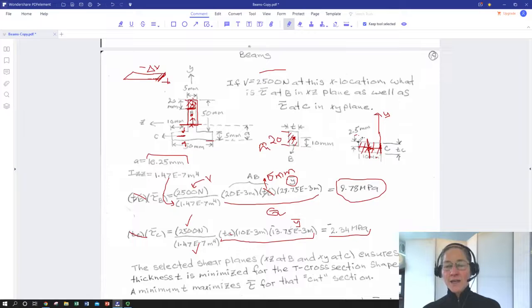So we can imagine, not surprisingly, our shear stress is going to be smallest out here close to a free surface where we don't have any ability to apply force. I'm looking, going in the x direction, negative x direction back here. And it's going to get bigger as I move closer into the center, because even though y bar isn't changing, A is changing as I get a bigger and bigger area. So that's the area versus location factor of Q, of that Q factor.